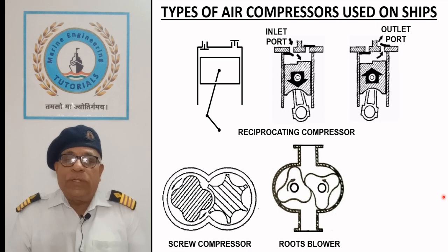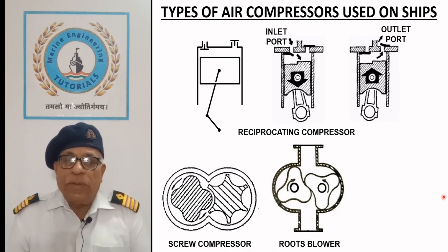It is used with inert gas generators equipped on product oil tankers for supplying the metered quantity of combustion air so as to control the oxygen content in exhaust gases. It is often used as vacuum pump on conventional oil tankers with centrifugal cargo pump for venting the oily vapors from their suction line.